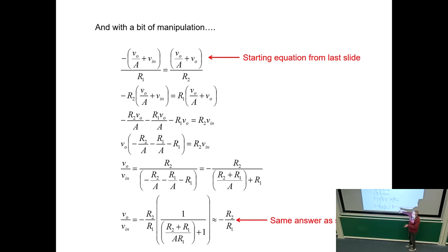So we can look at an amplifier circuit, and we don't care who the manufacturer of the op-amp is. We can just say the gain is going to be R2 over R1 for an inverting amplifier configuration. All we've got to do is recognize it as an inverting amplifier.